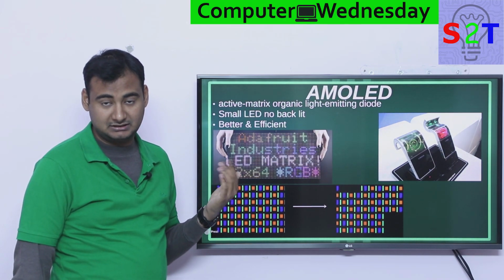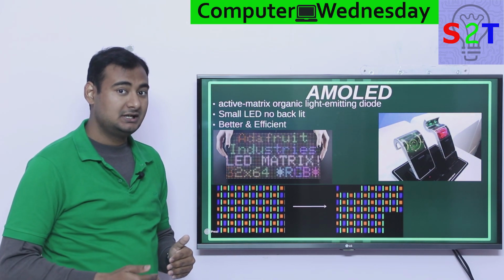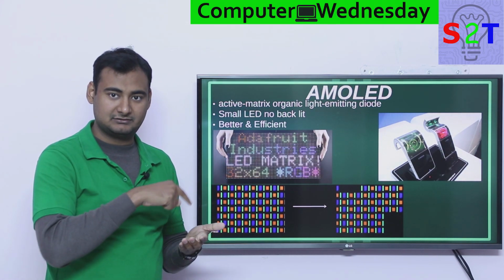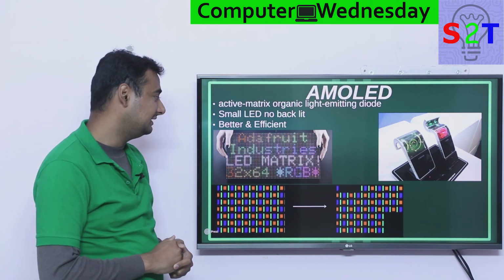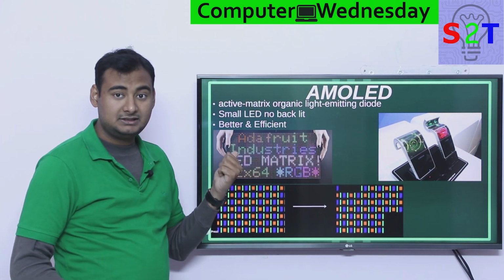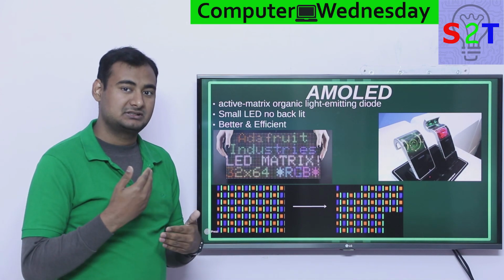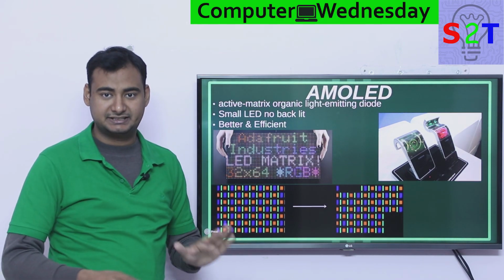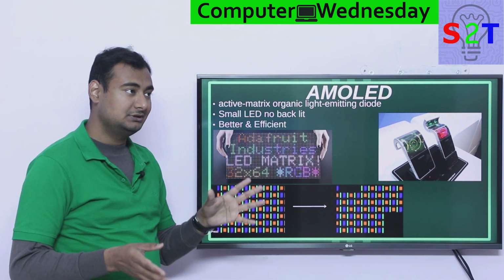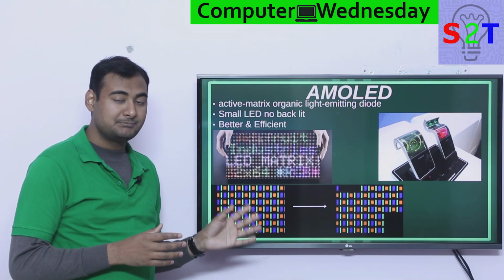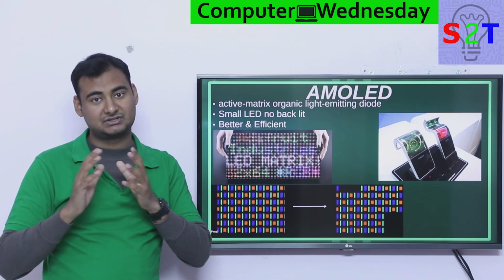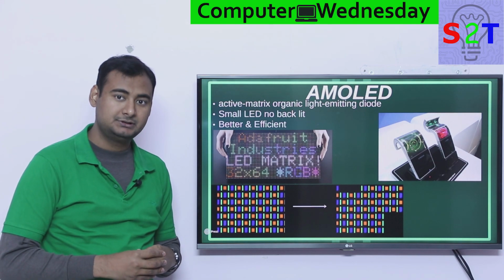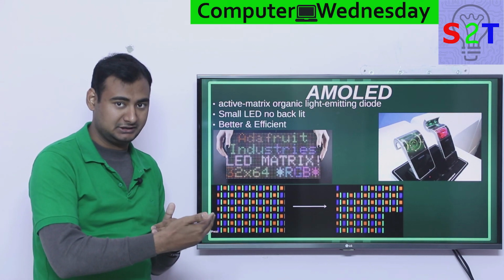It is also very efficient in terms of power usage, because if you are familiar with the whole idea of always on display, where you have notifications going on and things of that nature, this can do that. Why? Because the places that are supposed to show black are off, they're not doing anything, there is no backlight there. So if you compare the power usage of an AMOLED display versus an LCD display, AMOLED is upwards of 10 to 15% more efficient.